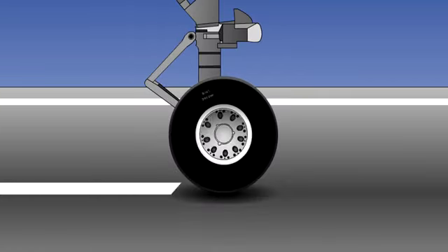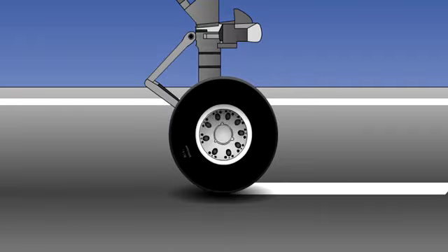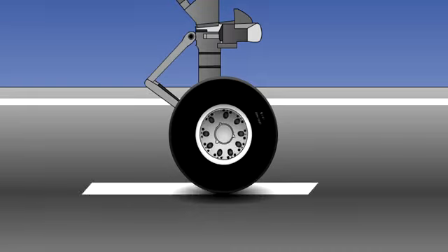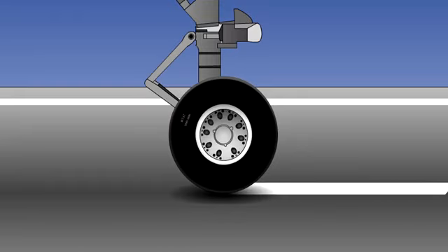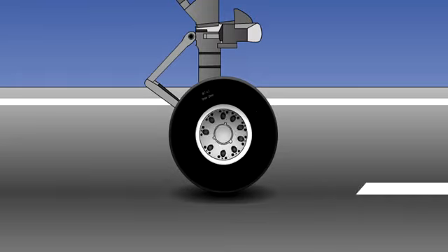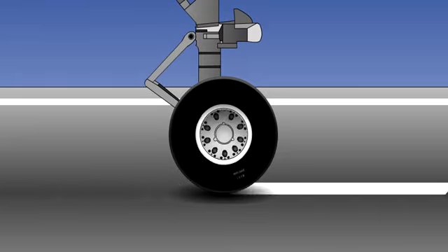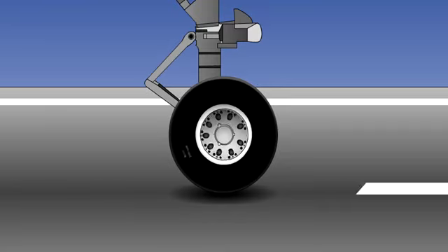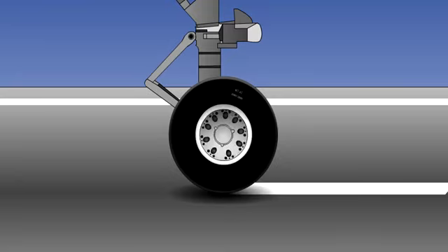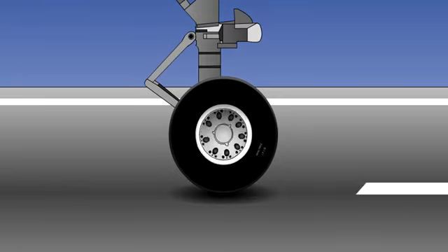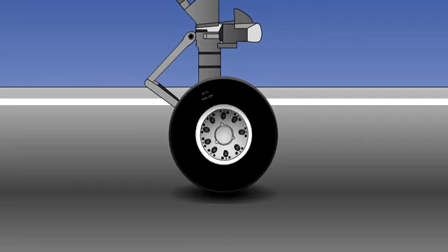When in service, particularly during heavy braking, there is a tendency for the tyre to rotate or creep around the wheel. This creep, if excessive, will tear out the inflation valve on a wheel fitted with an inner tube, causing the tyre to burst. Creep is less likely to occur if the tyre gas pressure is correctly maintained. The procedures for doing this are explained in the aircraft tyres lesson, but additional features to prevent creep may be incorporated in the design of the wheel, and we'll look at 2 such features now.